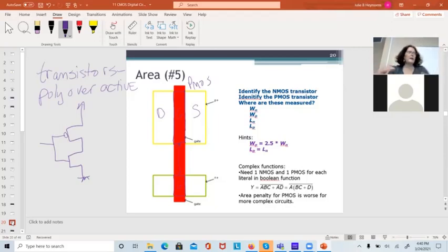Now, if we want to figure out how big the transistors are, my W for the NMOS device, and I said the NMOS device is smaller, the PMOS device is bigger. And also the NMOS device has N plus diffusions for the drain and the source. So we want to figure out how big the transistor is. We measure the W of the gate, and it just goes to the green lines, is the W in that dimension. The L is in this dimension. And yes, you'll get to do that a lot in lab 4 in 380. And that is for the NMOS.